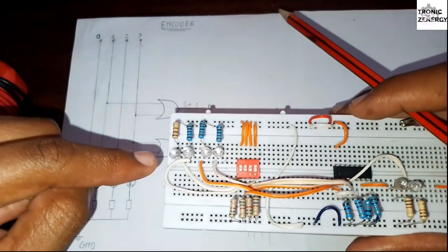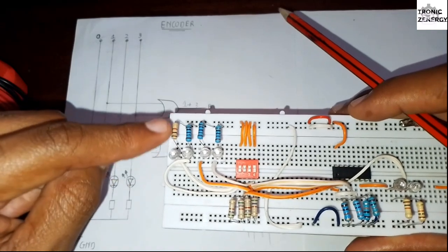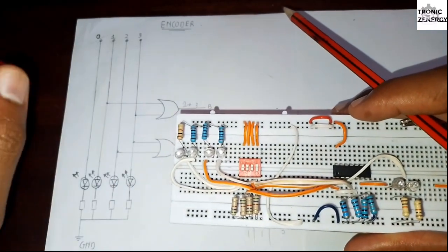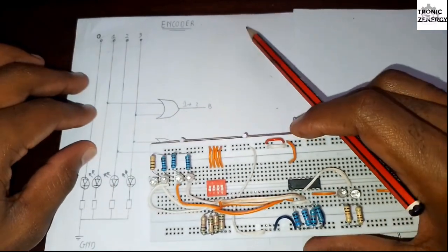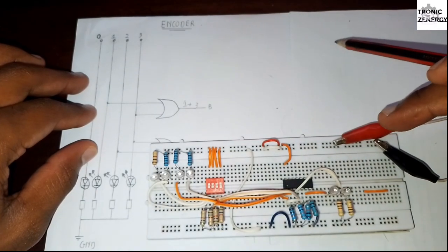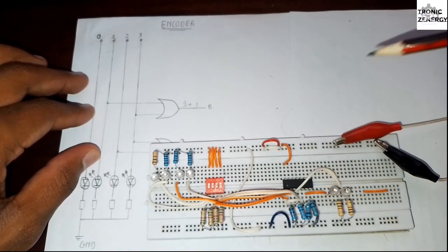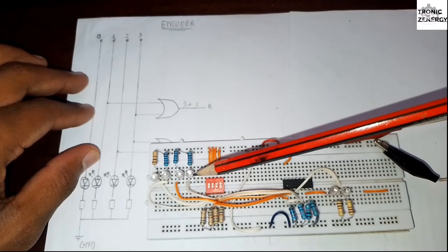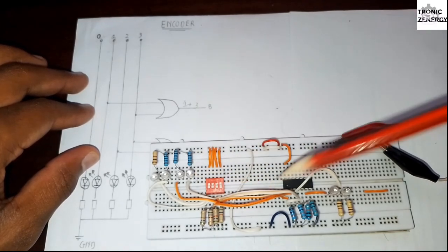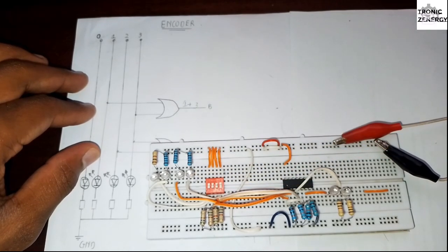The LEDs also require resistors to protect them from the voltages that I'm using. I'm using a 5-volt power supply. You can use any from 3 volts. If it's 3 volts, I think it's not very bad, you can just connect the LED directly, but for 5 volts you can blow up the LED.